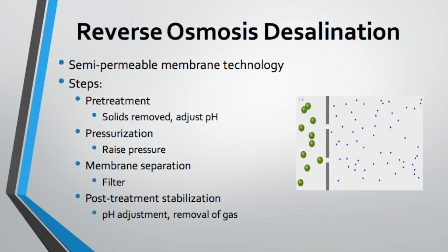Alright, so now we're going to talk about reverse osmosis distillation. Reverse osmosis utilizes a semi-permeable membrane to retain the solids containing bacteria, varying ions from solutions, and undesirable particles on the pressurized side of a selective wall, allowing only the most sanitary molecules to pass through, thus achieving potable water. This membrane technology is used on an industrial scale by applying a pressure that overcomes the osmotic pressure to transport that waste-depleted water through the membrane, which is a dense layer in the polymer matrix.